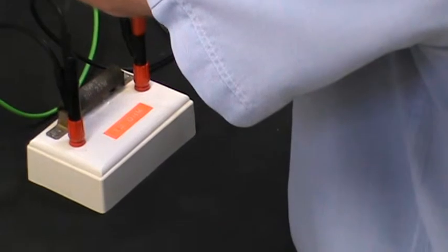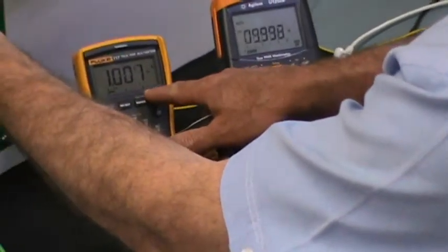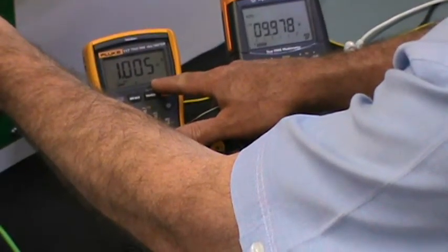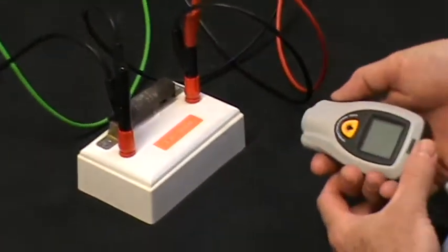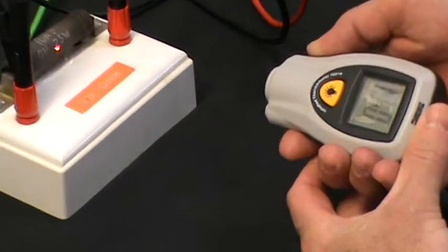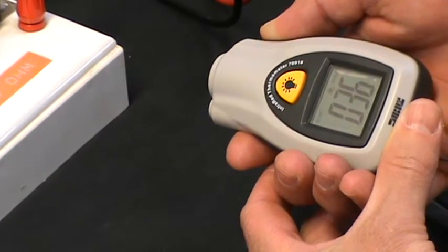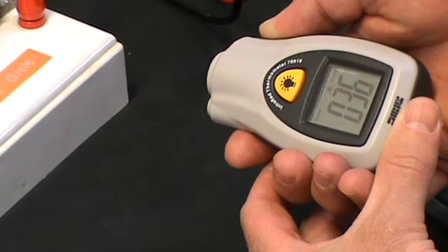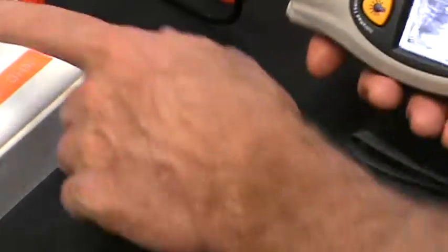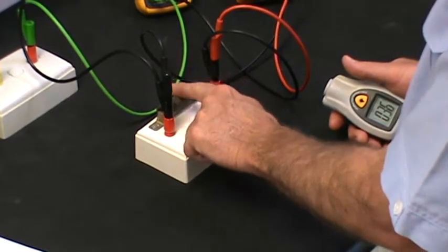So let me try that. Goes up to 10 volts. The current's increased to 1 amp, or thereabouts, almost at 10 volts. And let's have a look at the temperature on that resistor now. Now you can see the temperature has increased significantly. It's gone from 23 degrees up to 33 degrees. 36, 37. Keeping in mind it's now 10 watts, and I feel that resistor, and that's got quite warm to touch.